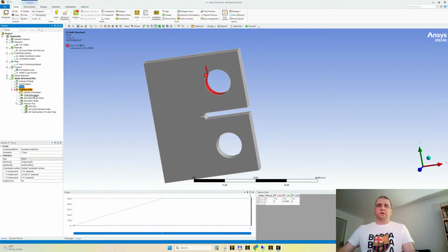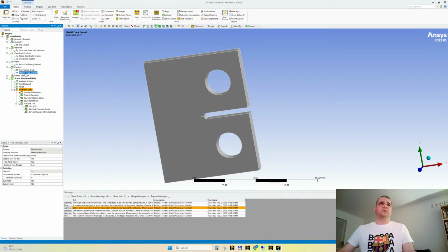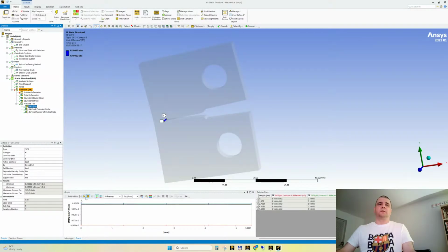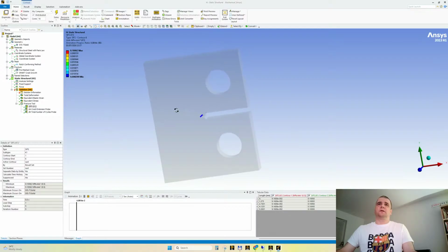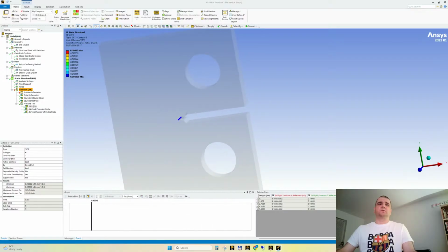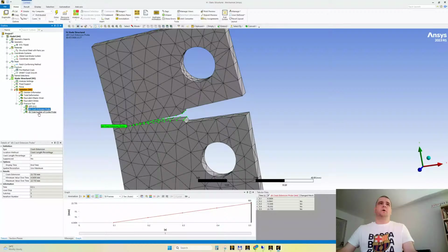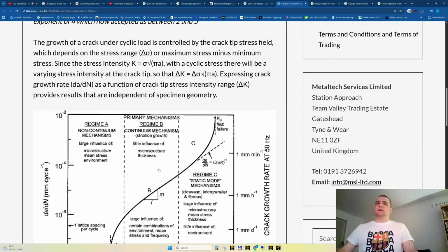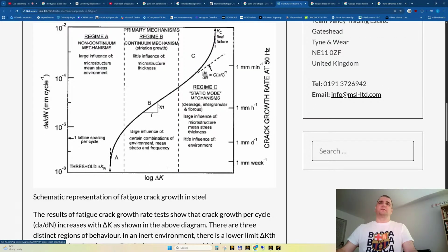Okay. The purpose of this live stream was to initiate you in the application of the smart crack growth. I have done this. I have also led you to obtain the crack. And what I will show to you is also how to make this plot, dA over dN, yes? In order to describe the linear portion for fracture, let's say.